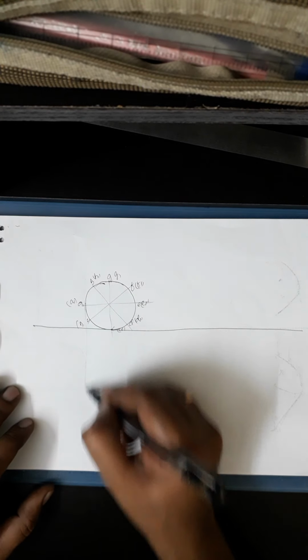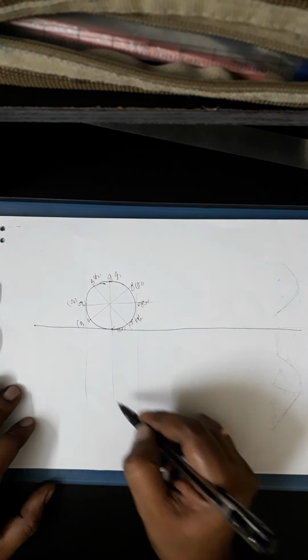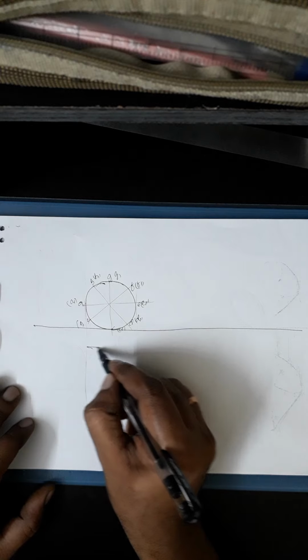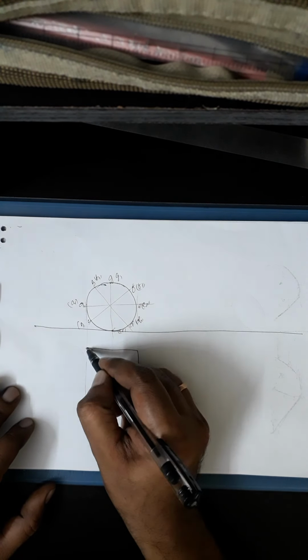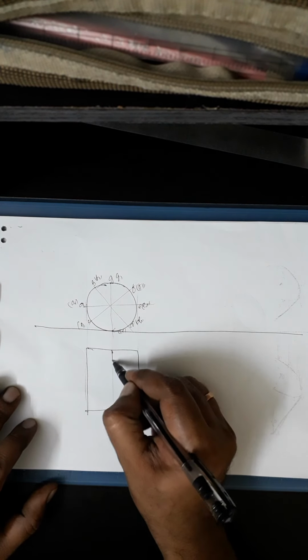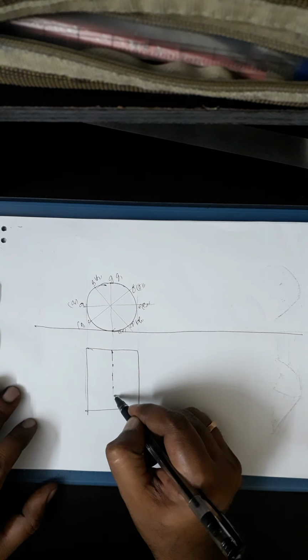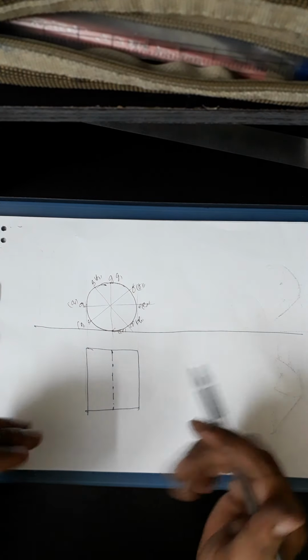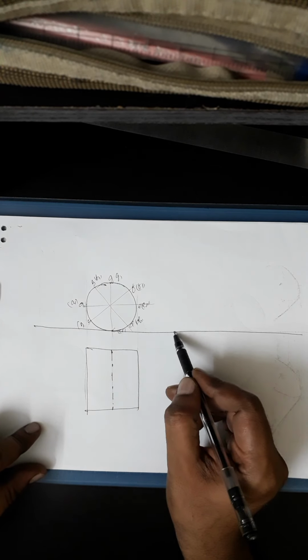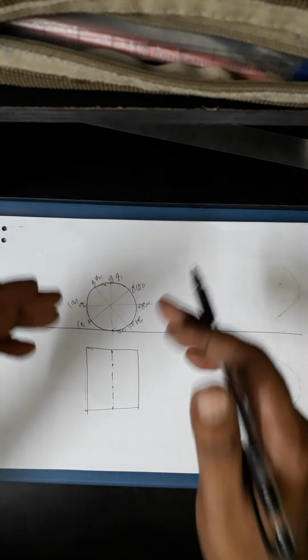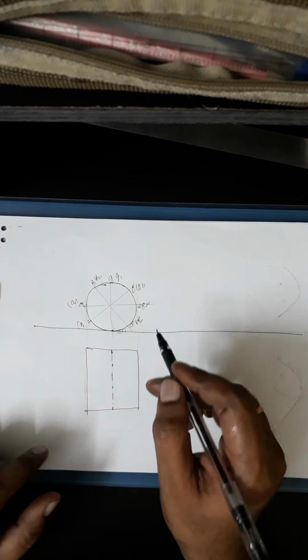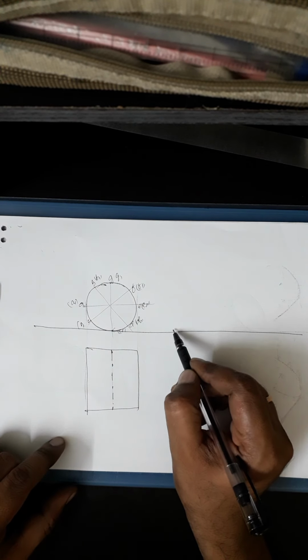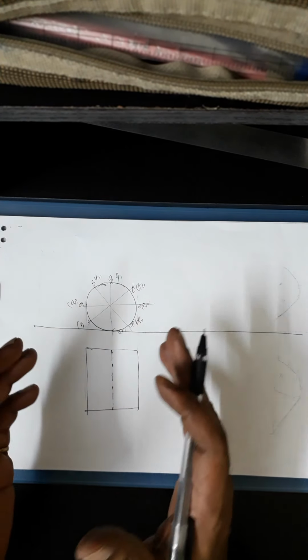So then this is my top view. So the height of the axis is similar to the prism. When it is resting on HP, I told you, when it's resting on one of its rectangular surfaces, you'll go for drawing the edge on the XY line, then you will draw this view directly in VP. And if it's resting on the longer edge, then you're going to have a corner to rest. In that way, you can directly draw in 2 steps.